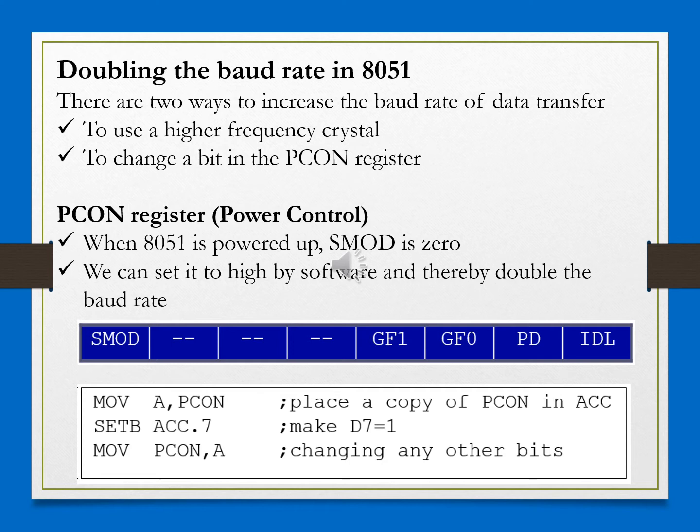When it is 0, then the machine cycle frequency, as we discussed in the previous discussions, will be divided by 32 by the UART circuitry. So what you get will be 28,800 hertz. That will be the frequency used by timer 1 for deciding the baud rate, when SMOD is equal to 0.